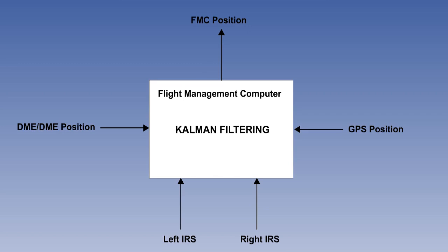The later generation of inertial systems, which are generally known as Inertial Reference Systems, or IRS, are usually part of an Integrated Flight Management System, FMS. In the Flight Management Computer, or FMC, there are usually 2 or 3 IRSs, each generating its own present position. These IRS positions are compared with independent sources, such as Global Positioning System or GPS, and computer-generated calculation of crosscut positions, which have been obtained from ground-based radio beacons called distance measuring equipment.